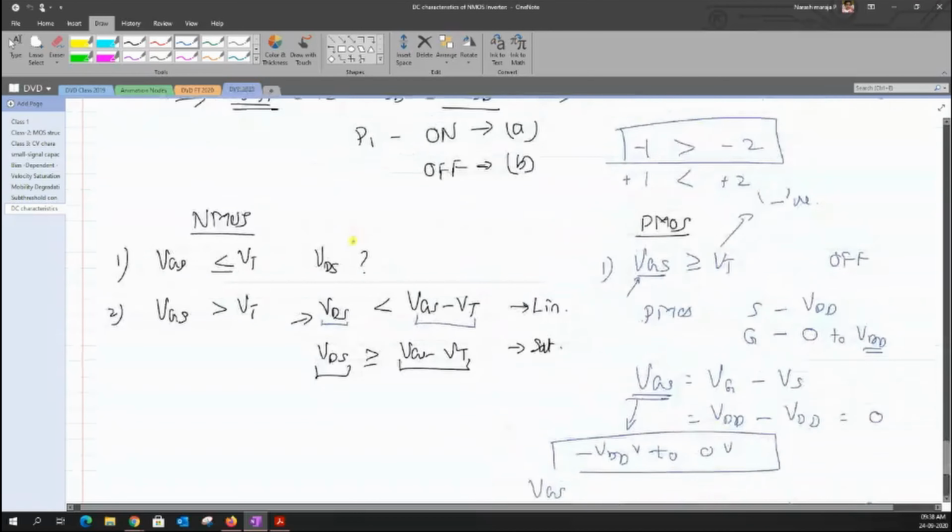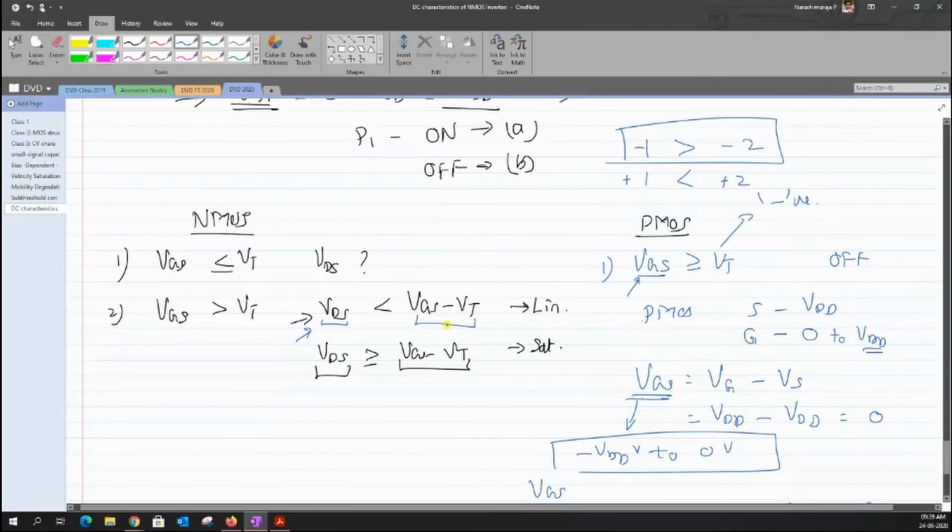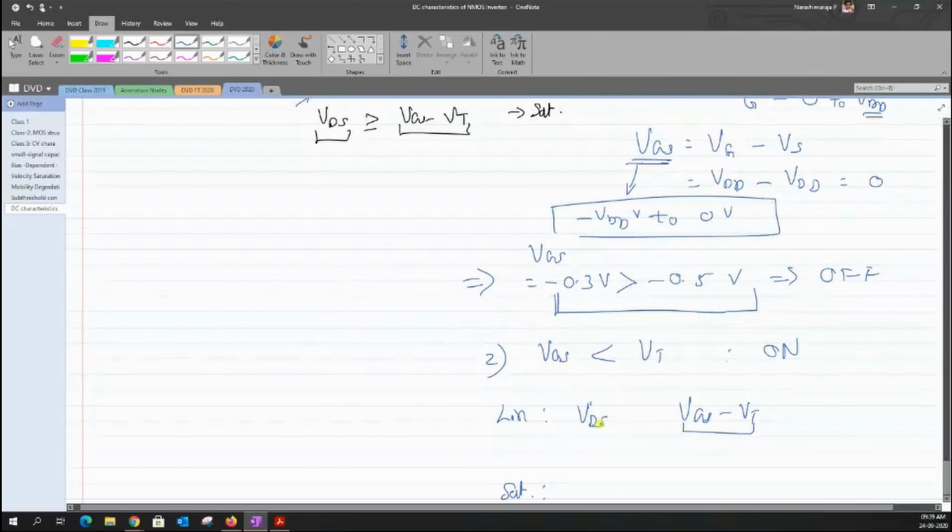However, we said over here, in this case, that the VDS value of an NMOS device, if it is less positive compared to the VOV value, then the transistor is in the linear region. So here again, I would say the same argument. In this case, the VDS of the PMOS has to be less negative compared to the negative value of VOV. So how will I say that it is less negative?